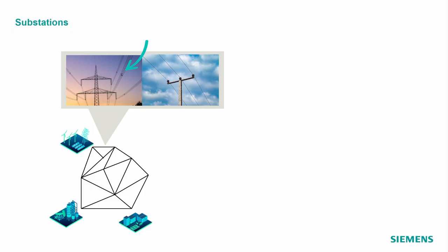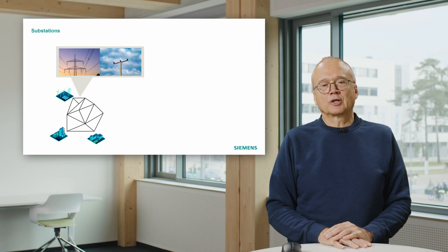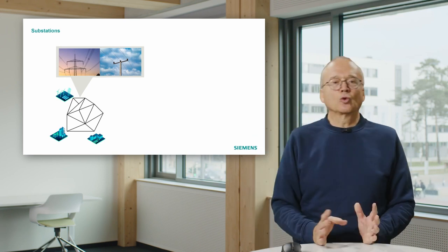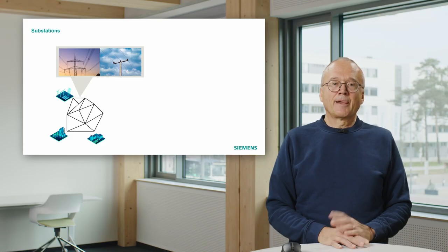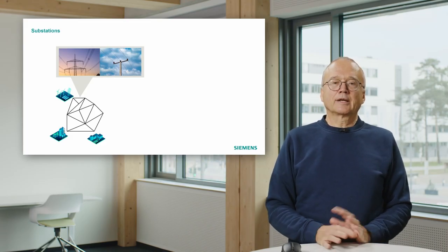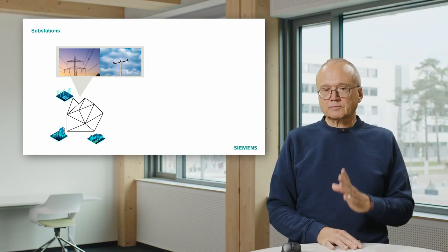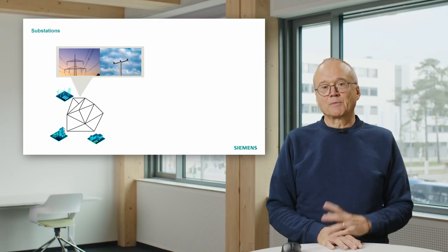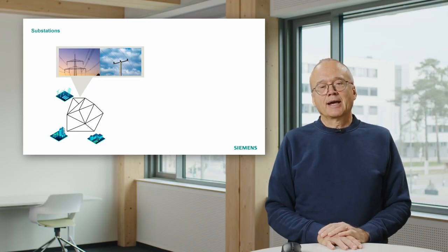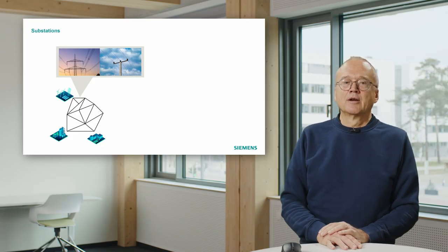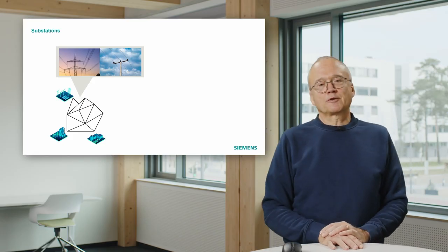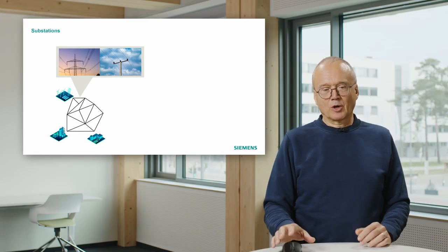It reduces the electrical field strength around the conductor. That's why it's a normal case for an extra high voltage line. On the right-hand side, you see a distribution overhead line, medium voltage. In this case, 1 system, that means 3 conductors. And there we use just single conductors for the individual phases because the field strength is much lower there.